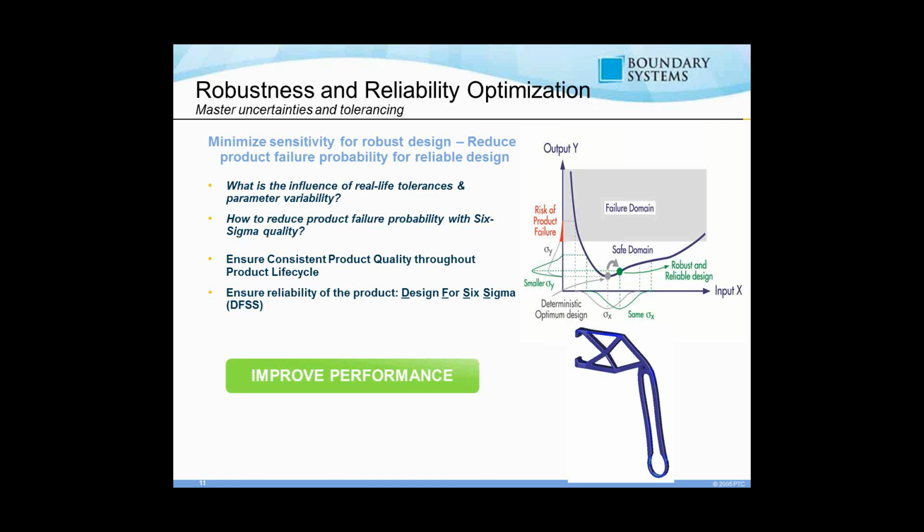Well, with Optimus, you can tell it what your expected variability is. For example, in this graph over here, the gray point is our mathematically best or optimal design point. But with some manufacturing variability, when we look over on the left-hand side, this gray bell is going to be the performance variability. And we realize, okay, some of our widgets will fall in our failure domain if we use the mathematically optimal solution.